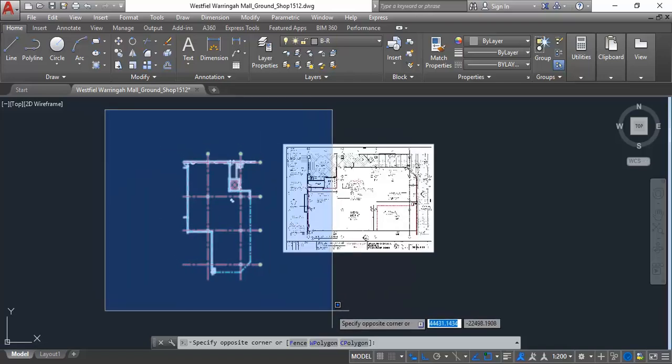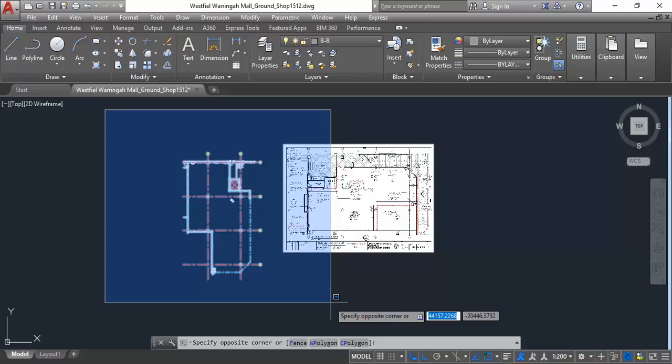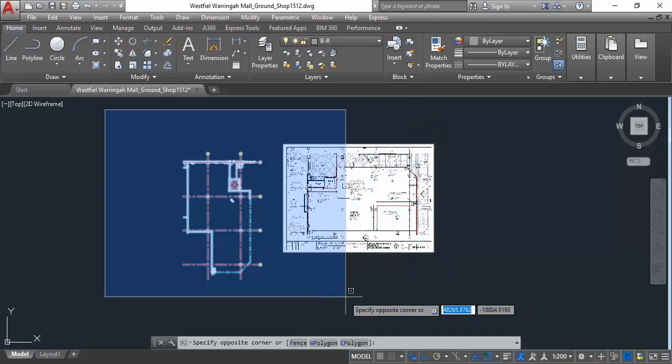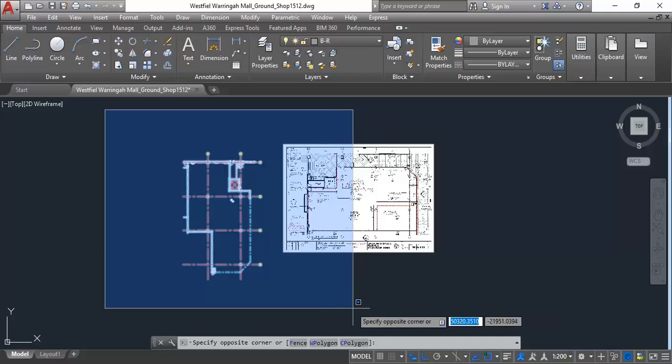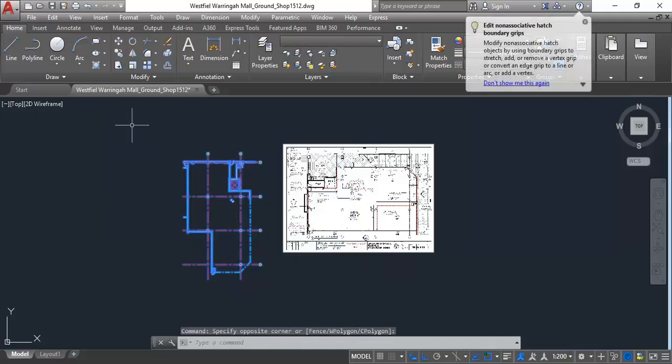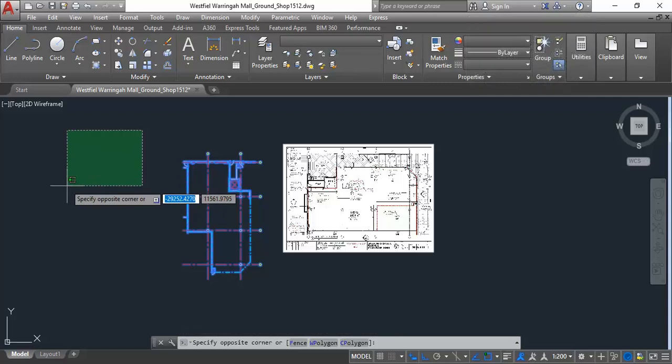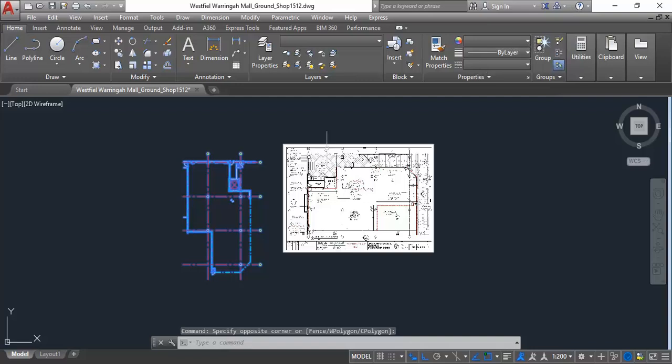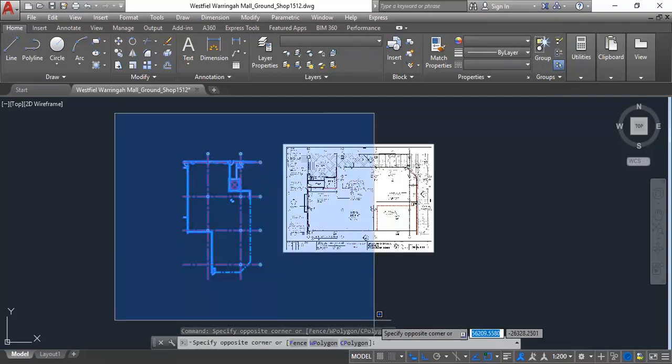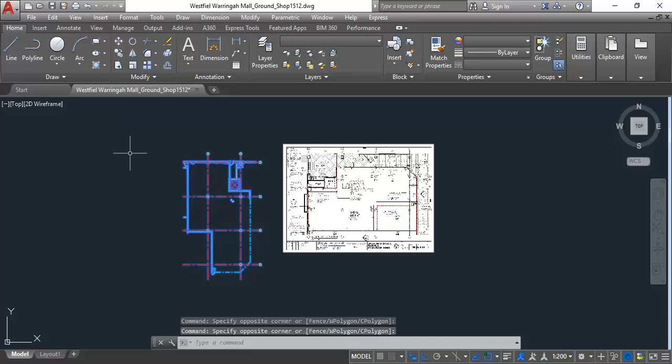And when it's blue with a solid outline, do you remember what that means in AutoCAD? Only selects the things inside. So I can go over the image. As long as I don't go completely over it, I'm not going to select it. Okay, and that's called a window. If I go the other way, to the left, it's a crossing window, which would select the image as well, because it selects anything it's touching. So again, really important that you know those two different options for selecting, and I think here definitely the blue one, going left to right, should be much easier.